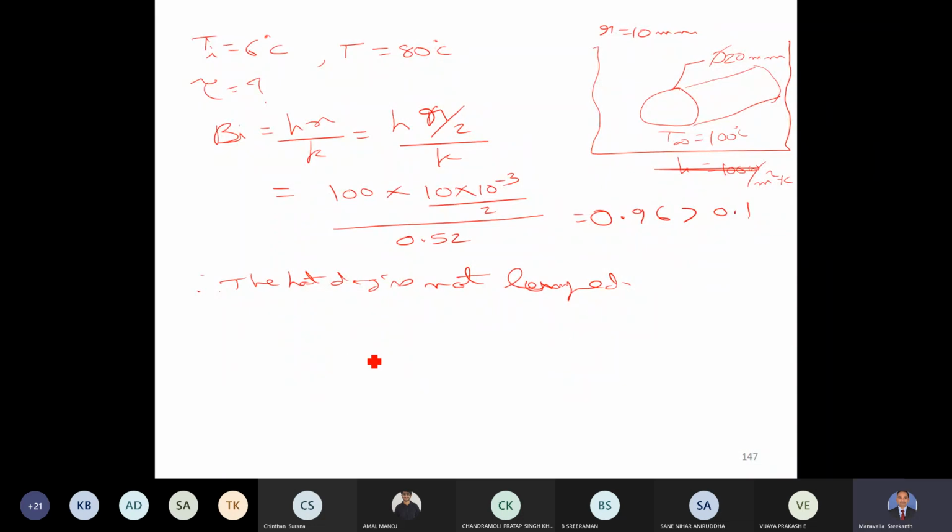We are told that it's a long cylinder. The words long cylinder, and we are also given the diameter, mean that it is an infinite cylinder. So we'll have to use the concepts of an infinite cylinder. Now open your data books and turn to page number 77. On page 77, you have a graph titled long cylinder, temperature time history at center line.